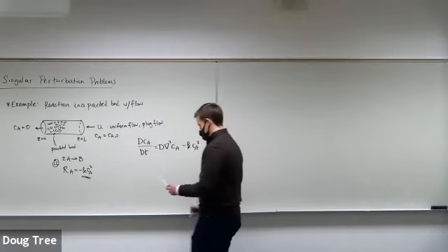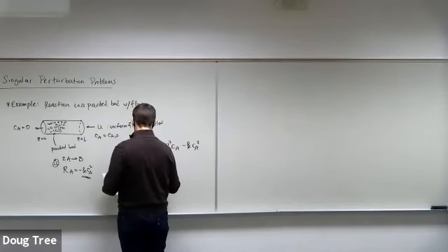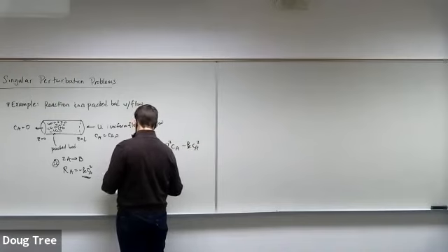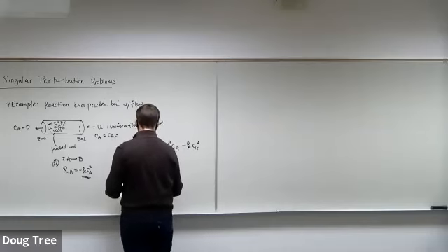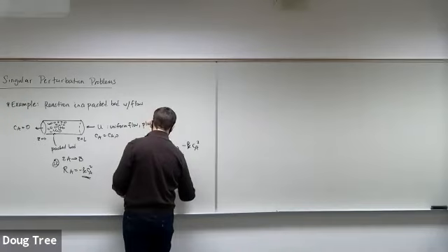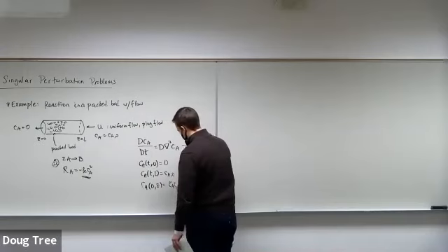And we have boundary conditions: C_A at space 0 is equal to 0, C_A at time and L is equal to C_A0. And there's some initial condition I'm not going to care about, so we'll call that C_A tilde function.